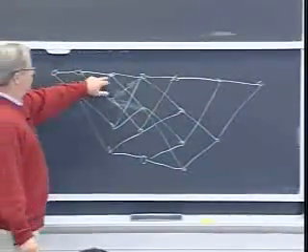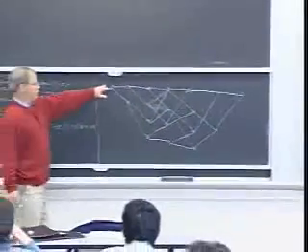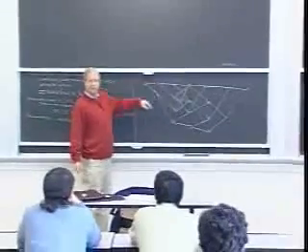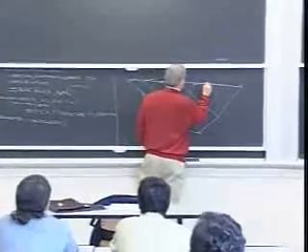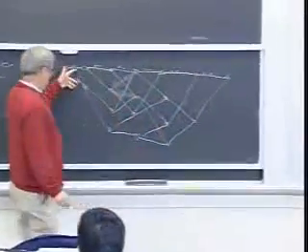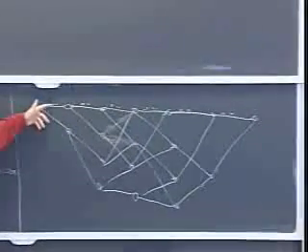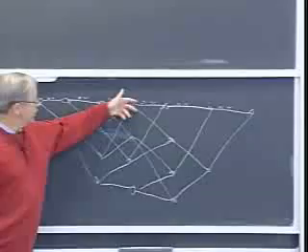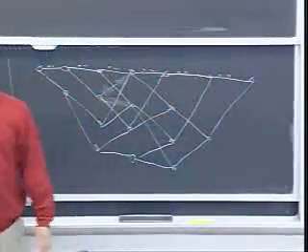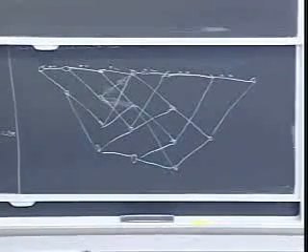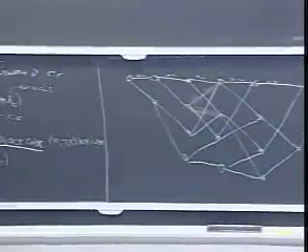All right, which is 1, 2, 3, 4. I did it correctly for this code, actually, because each of these is going to have a two-tuple output on it. Here, each of the information bits causes a two-way branch, no matter where you are in the trellis. So here's 1, here's 2, here's 3, here's 4. That's the end of them. We wait for nu equals 2 to let the states converge back to 0. All right, so that's a trellis representation of this 12, 4, 5 block code.